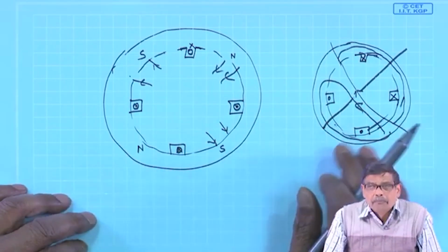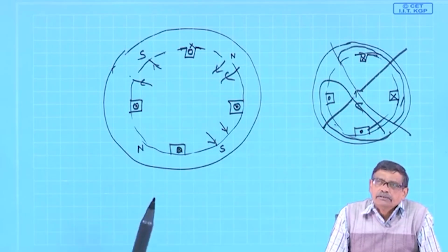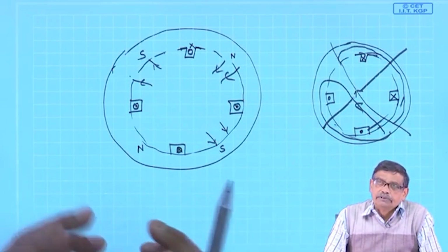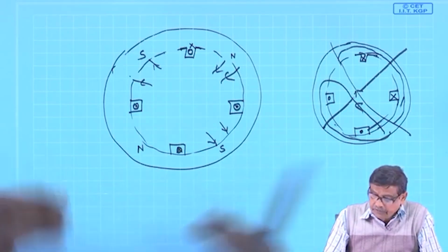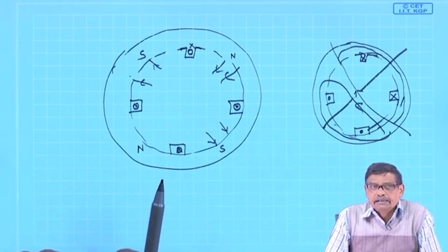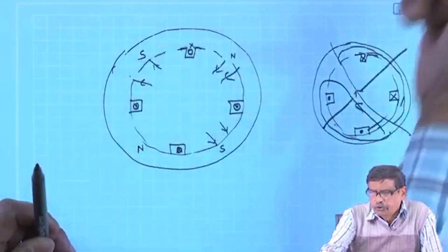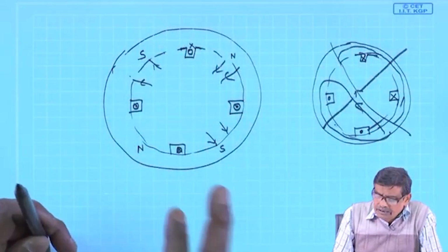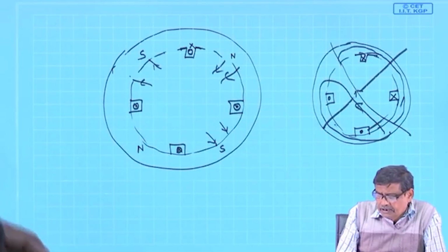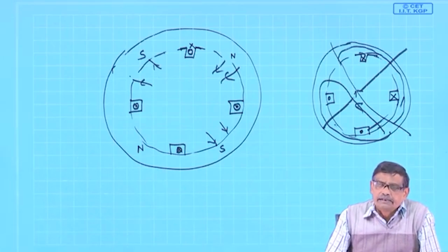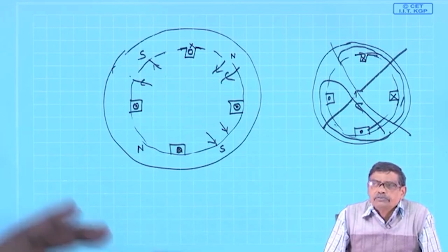We will not go much into this, simply because earlier these were very nice methods proposed after a lot of research work. You have one 3-phase winding, but some terminals should be available to the users. By interconnecting those group phases, you can generate 2 poles in the ratio of 1:2.